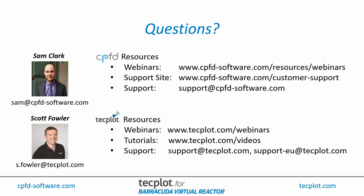Is it possible to convert PLT, so that's a Tecplot format, to human readable format? So yeah, Tecplot PLT format is a binary format, and within Tecplot 360, you can go to the File menu and say Write Data, and that can export it to Tecplot's ASCII file format. We also have under the Tools menu the ability to write it out as comma separated values. The comma separated values only has the capability of writing out values that are at the nodes, though it doesn't write out values that are at the cell centers. So just be aware of that.